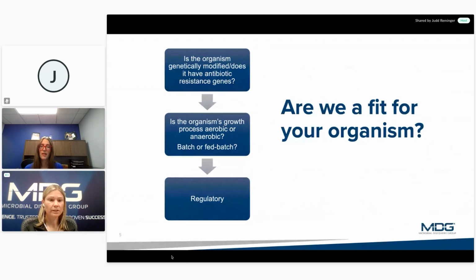Yeah, so Shannon touched on most of this in the first slide. Again, is an organism's growth process aerobic or anaerobic? We do mainly work with Bacillus, so those are highly aerobic. So both in lab process development and on our fermentation side, we aren't quite there for anaerobic growth yet. We mainly do batch fermentation. But as Shannon mentioned, we are able to do filter sterilization, both in lab and again on the fermentation scale as well.